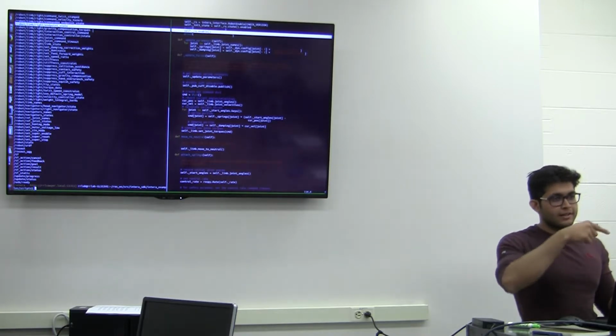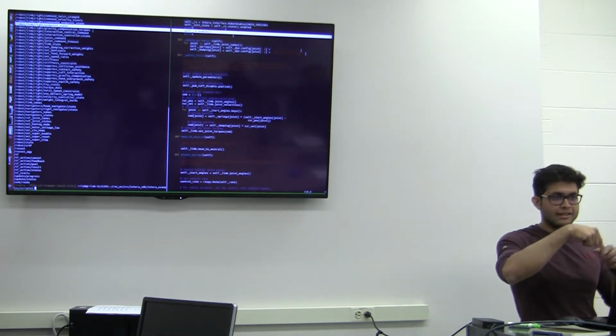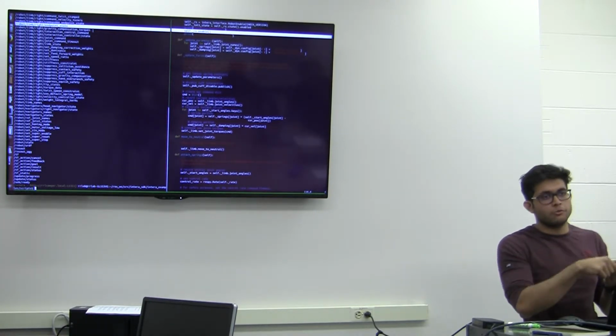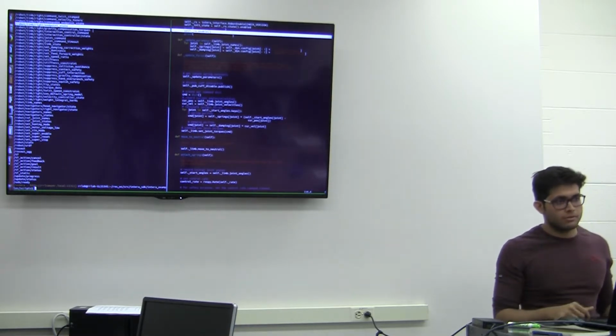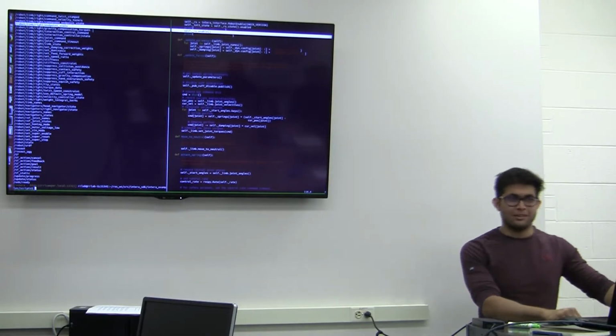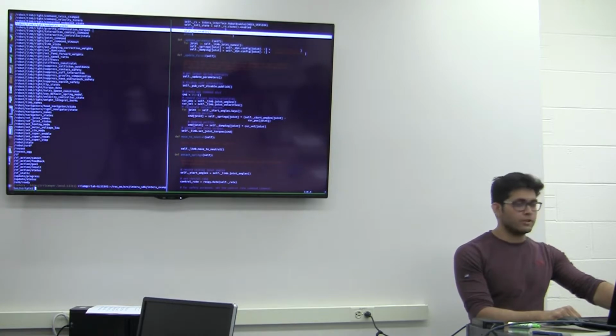So that's why they use their force calibration parameters to make sure that the angle is correct and the drill is not facing any external force. Like it can break midway, right? And you don't want that. Drill is costly, part is costly. So that's where they use these robots. Not this one. This is much more precise than what they need for that. But again, that's why the joint forces are important.